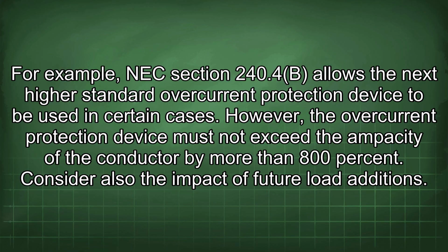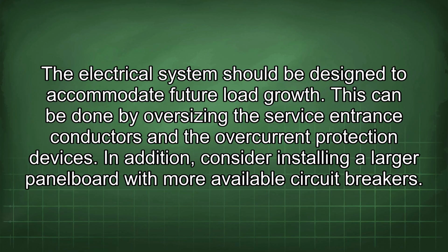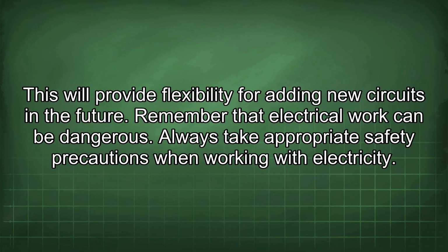Consider also the impact of future load additions. The electrical system should be designed to accommodate future load growth. This can be done by oversizing the service entrance conductors and the overcurrent protection devices. In addition, consider installing a larger panel board with more available circuit breakers. This will provide flexibility for adding new circuits in the future.